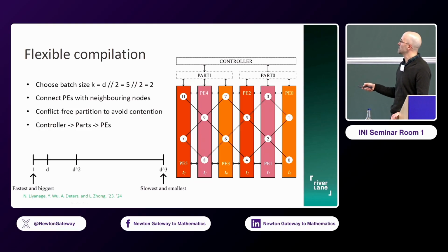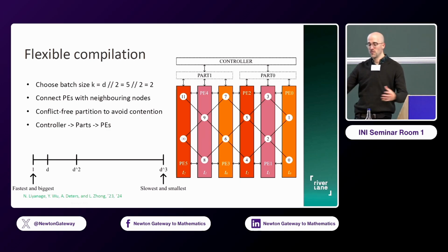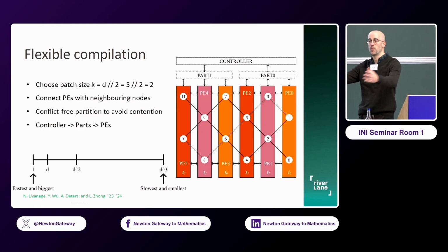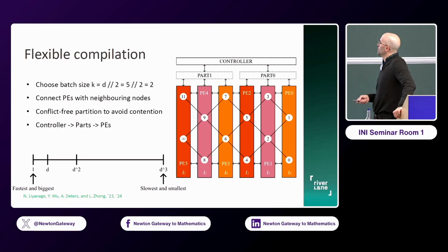This would be the fastest possible implementation of this problem, but it would be also very big, because we would need lots of these independent workers working simultaneously that would kind of occupy our FPGA. Right? On the other hand, we could have no parallelism at all and just have one worker, and that would be just like having a serial implementation of this decoding process.